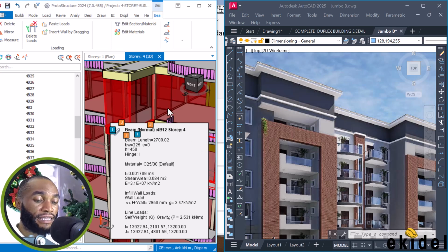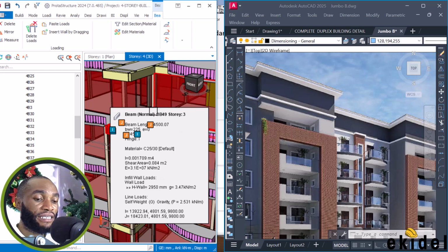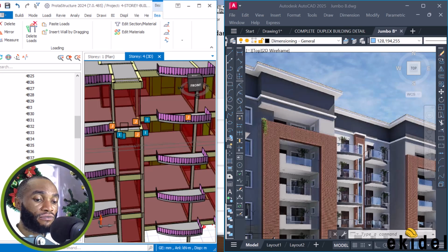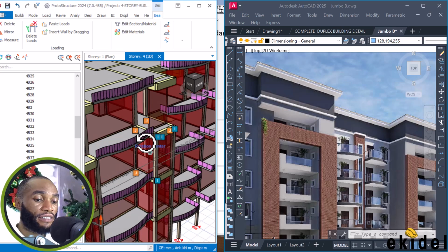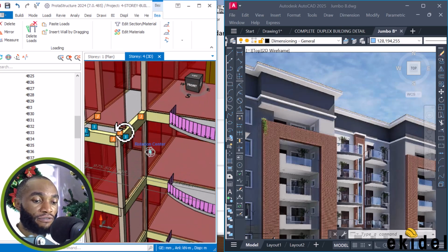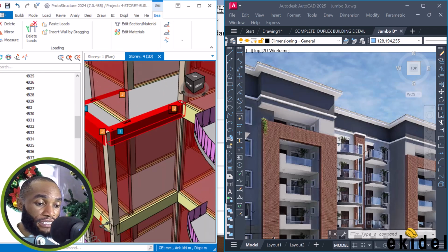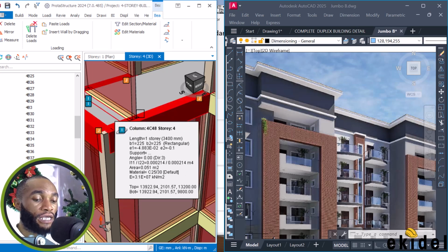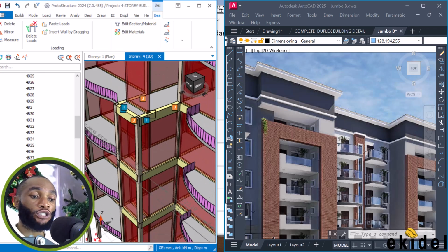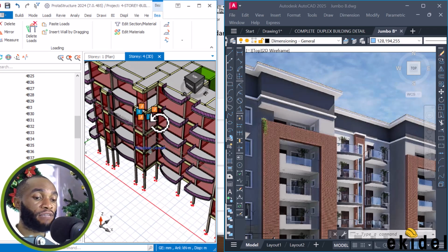Let's see what we have now. That's fine. Let me see what I have. Rotate now. That's fine. So with this now, I can choose to put a partial load here. You can see this place here is meant to have a wall load. Only this small portion here is meant to be removed. So there should be a partial wall load here, which I can show you how to do, but that will be later.